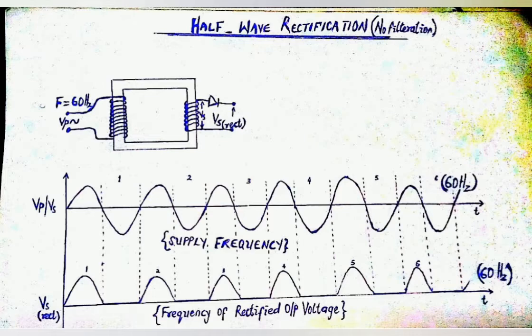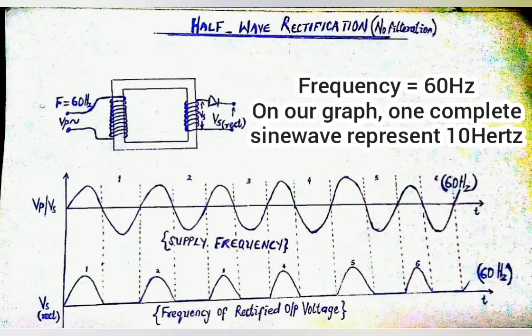Here, output voltage from the diode rectifier is usually pulsating in nature. The pulsation is at intervals determined by the frequency of the input voltage. After rectification, the AC nature of the input voltage has been altered. The aim is to achieve a form of electricity likened to that produced by batteries.